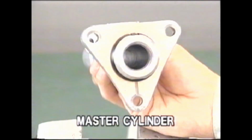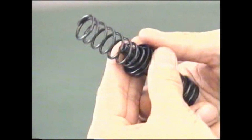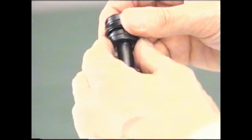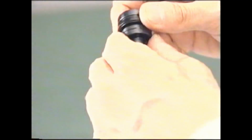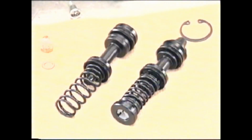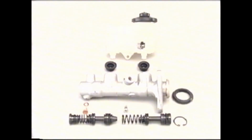Inspect the master cylinder bore for scoring or corrosion. Inspect the piston and cups for wear, scoring, cracks, or swelling. If any of these need replacement, use the parts from the cylinder kit. Apply lithium soap-based glycol grease to rubber parts shown here.